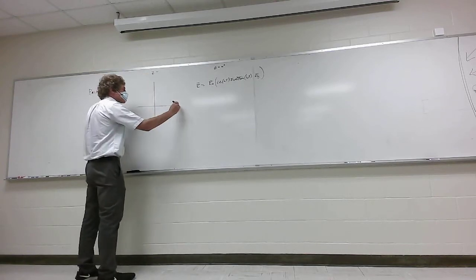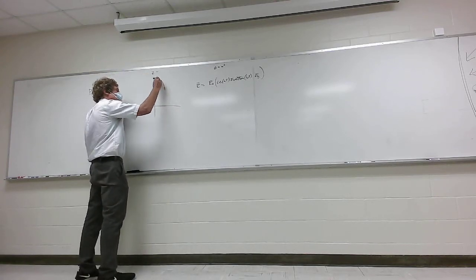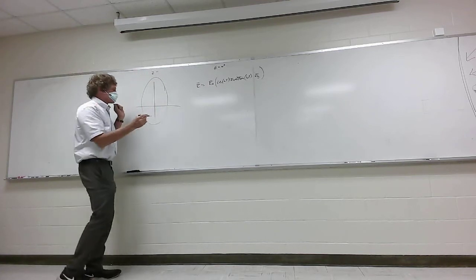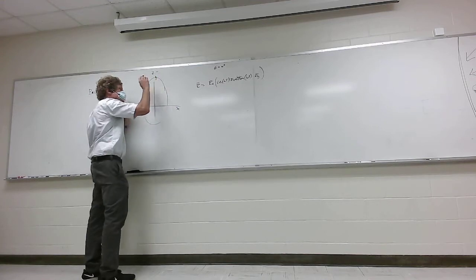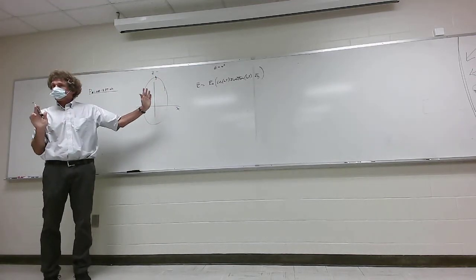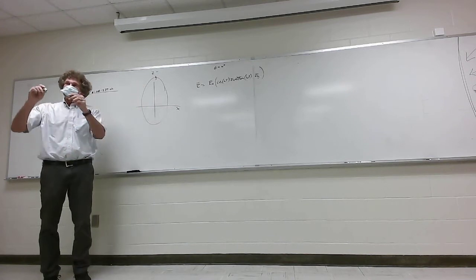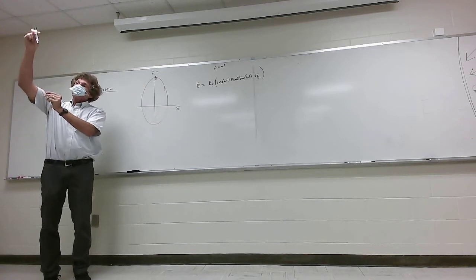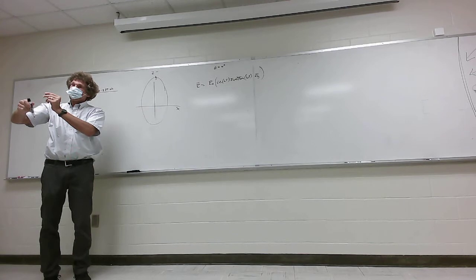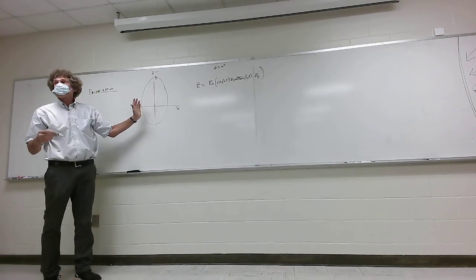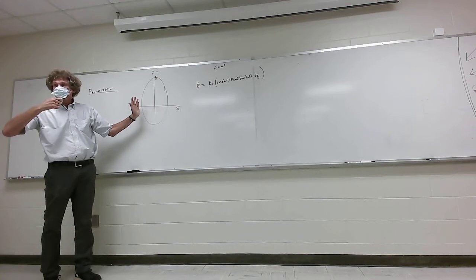For instance, if you can have an elliptical waveform that looks like this, the tip would trace out that pattern. It doesn't matter the axis, just following this. I can make that happen mathematically very easily. Y'all follow me? Now, the reason they would want that is because the dominant scattering from raindrops is vertical. If they're falling vertically, do y'all follow me on that? So you would want the major component of the electric field vertical because you'll get a larger bang for your buck in terms of return.